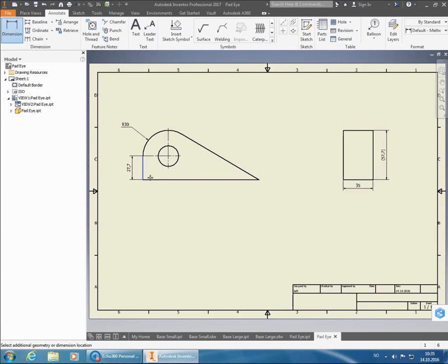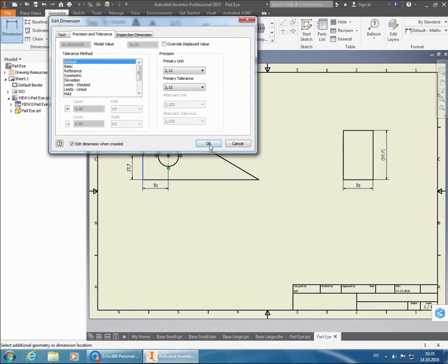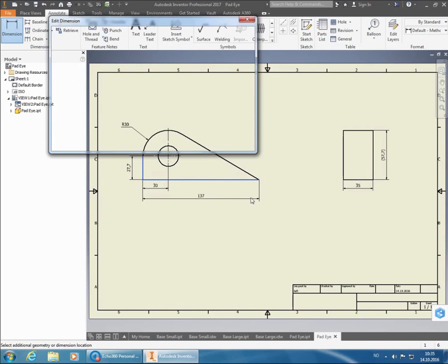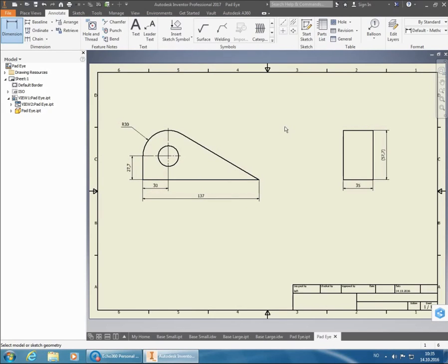And then we'll put in the length over to the center point. We want it connected to be placed on the same line as this dimension. And we want the total length of the pad eye. And before we create the dimension for the hole going through here, we're going to put in also as a reference the angle in here.